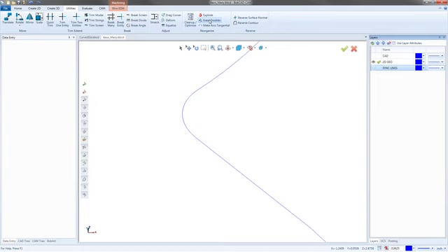But there's certain scenarios when if I have 2 lines crisscrossing and there's duplicates on them, I don't want them to be one individual line crisscrossing another. I might want it broken into 4 separate lines. So if you use Clean Up Optimize, it's going to rejoin that geometry. If you just erase doubles, it's just getting rid of the doubles.